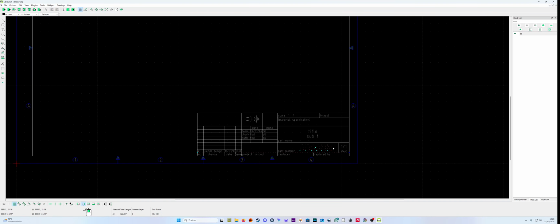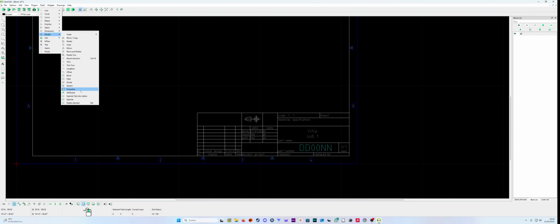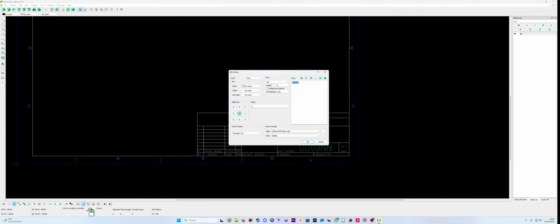So I'm saying, you know what, wait a moment, I'm gonna say, okay, this should be the flange. Oh, wait a moment, I was a little bit too enthusiastic. Undo. I'm gonna say here, edit tools. How it was, tools, modify. Yeah, modify. It was properties. I'm gonna say properties, and now you see I'm gonna change it to flange